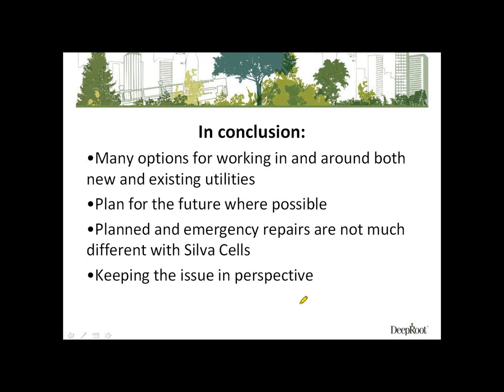At some point there might be some, but the biggest part of the tree roots will come through, and then as the tree roots come out of the system, they will push that geogrid open, and at a time when the roots are big enough, they should actually be able to separate that geogrid enough to get through. Also, the root will put a larger root down, or start as a larger root and continue to telescope out. So, is it ideal? It's not the ideal thing, but of your different choices of being able to spread your system out, it is a good solution.